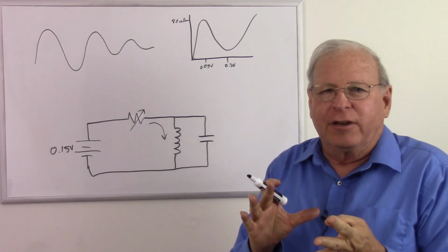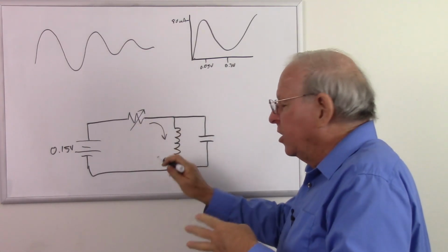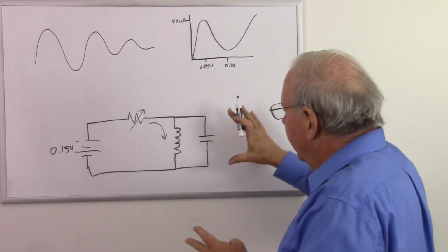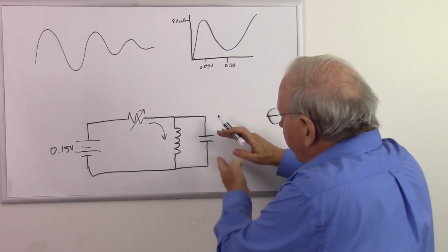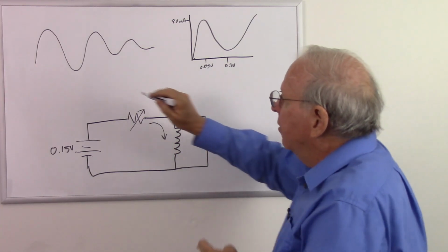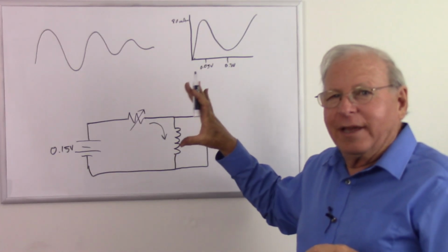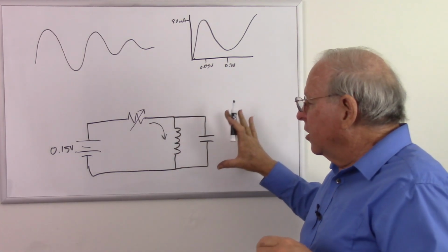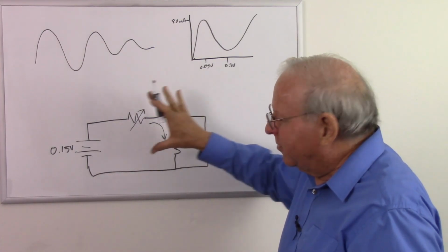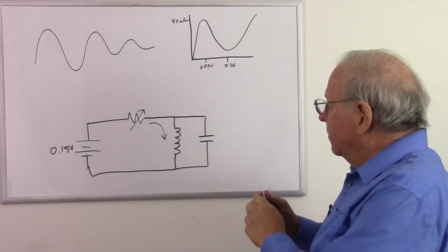What happens when you push current into an impedance? You get voltage across it. More current, more voltage. So we're pushing current in, giving us more voltage, pushing that voltage up. And then when this voltage goes down, we want this to go to a high impedance, so it's no longer pushing current in there, allowing that to go down. Now, we have to follow this carefully because it's following Kirchhoff's voltage law and doing everything it should, but we have to remember which voltage is going up and which voltage is going down to make sure we understand what's happening. So here we go.